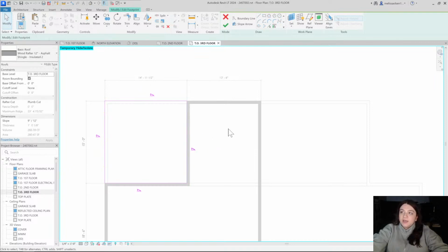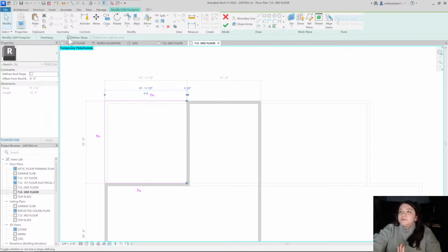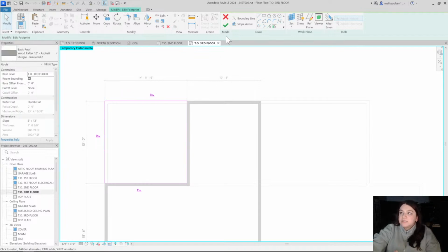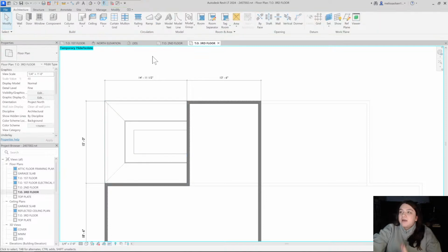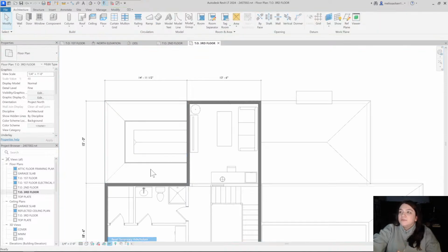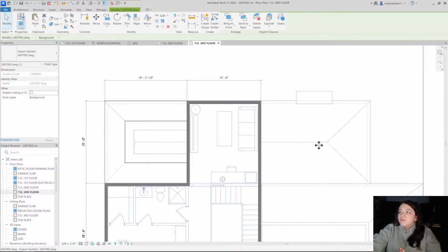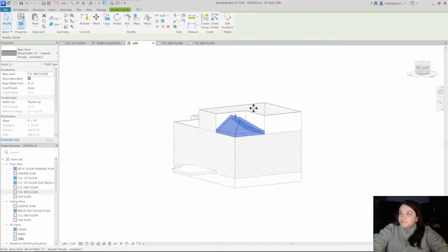Right now all these roof lines have this little triangle, which basically means a slope is associated with it. So I'm going to take away the slope definition for this one, and you'll see that it now starts to give you a roof with 3 slopes dying into the house, which is a hip slope, or a hip roof, sorry.